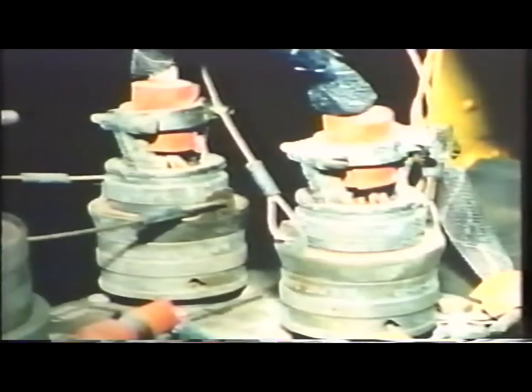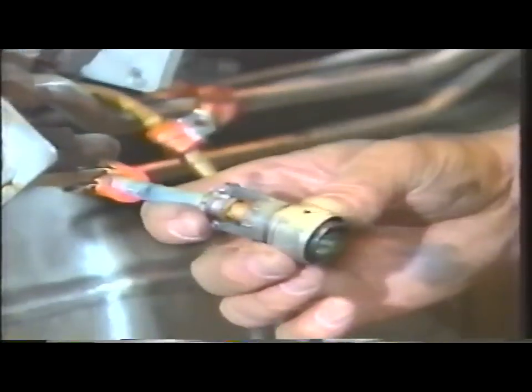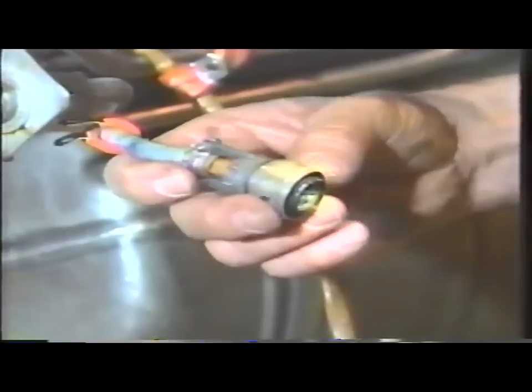Second, active and dissimilar metals are often left unprotected and in electrical contact. And finally, even a small amount of corrosion can make equipment inoperable. For more information on avionics corrosion, consult AC 43-4A, Chapter 4. Electrical connectors can be a particular corrosion problem due to moisture collection.